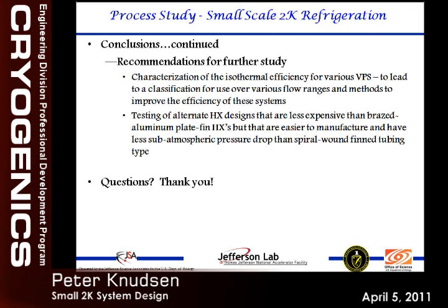The other one is testing some alternate heat exchanger designs, ones that have both very high heat transfer and low pressure drop, which is obviously very key for an atmospheric process like this. One of the ones that we're looking at is basically a wire fin tube with tall wire fins on it. And we're in the process of evaluating that.